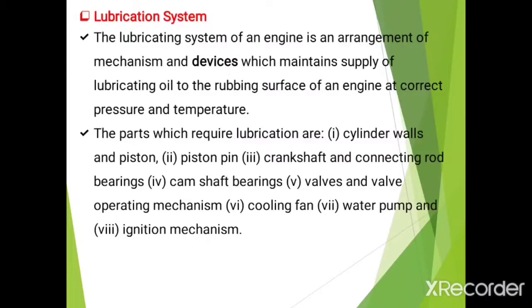Now there are some functions of engine oils. It provides a thin film between the moving parts and minimizes friction and wear. It also removes heat from the engine parts, thus acting as a cooling agent. The next one, it absorbs the shock between the bearings and other engine parts, thus reducing noise, and the life of the engine increases.